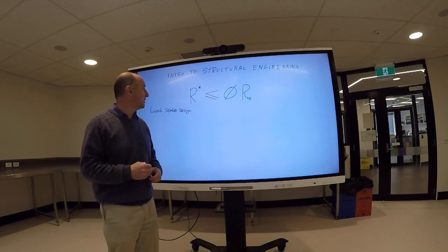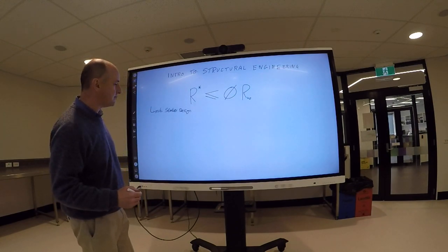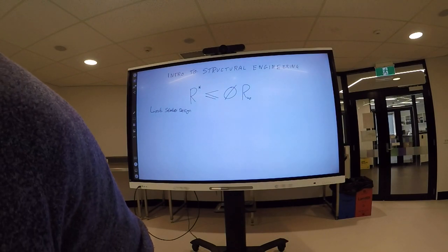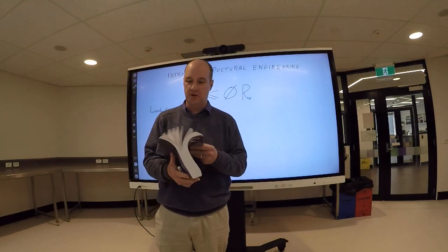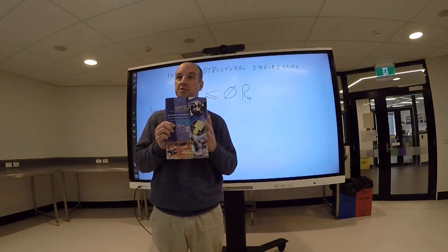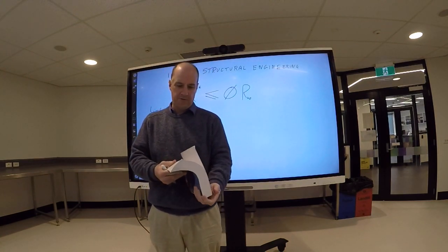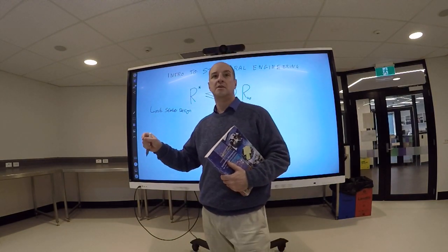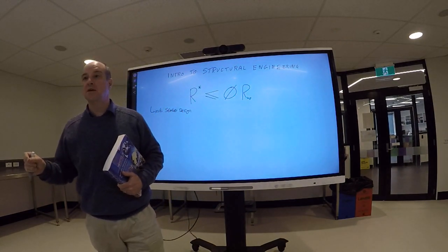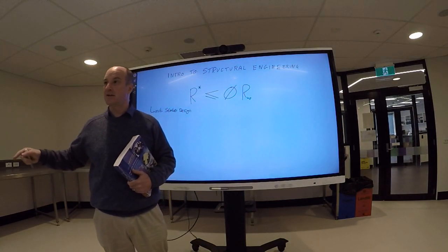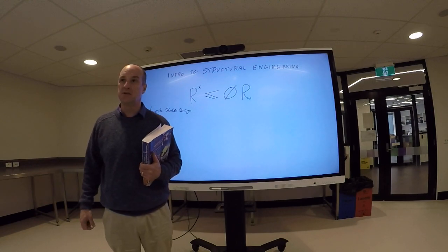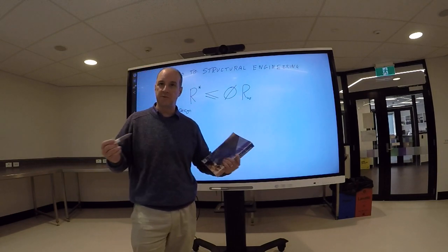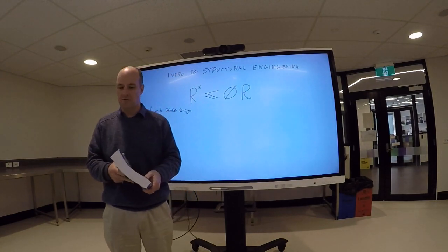Okay, so let's look at the load side of the equation. And here we have turned to Australian standards. This is a fairly old book, and this is just a collection of 5 or 6 Australian standards. The one we refer to here is called AS 1170. All the Australian standards start off AS for Australian standard. Sometimes they start off AS/NZS because we do a lot of this in partnership with New Zealand. The Euro codes are a similar idea, with a different set of numbers, and the way they're authored is different.